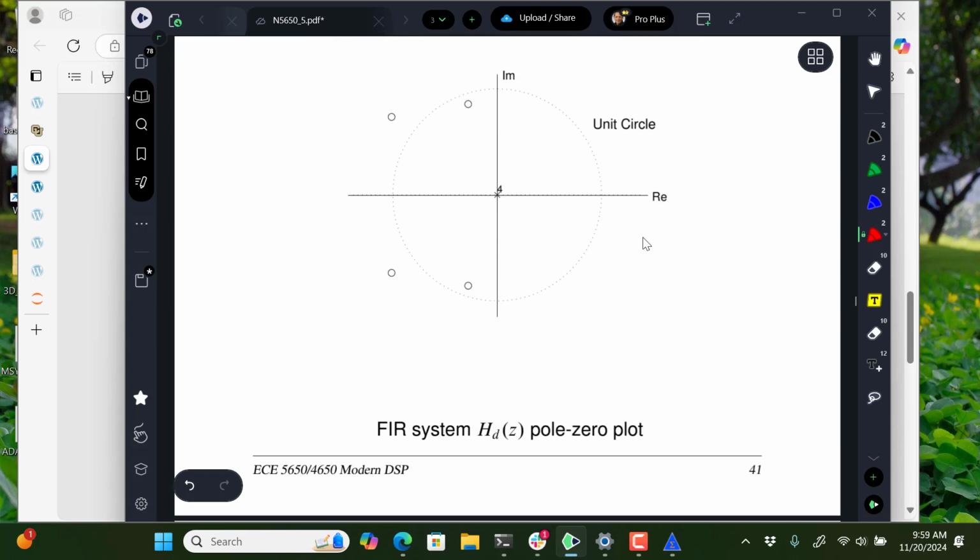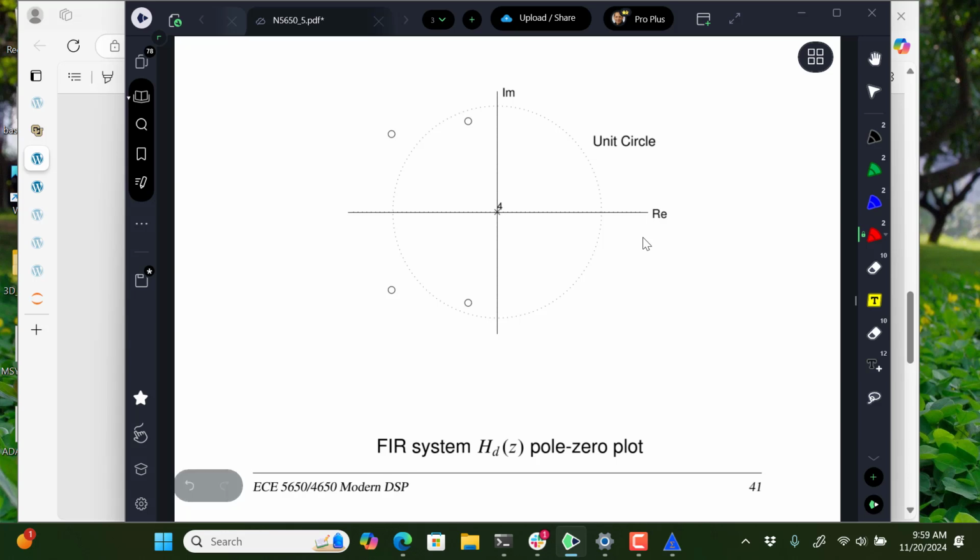So we could draw this picture if we were doing a different homework problem, but the basic problem is we're going to use an all-pass filter to represent the transformation of this into the minimum phase, or to relate the minimum phase equivalent, which would be that, and then we could go back to that by having what the all-pass would look like to convert from the minimum phase back.